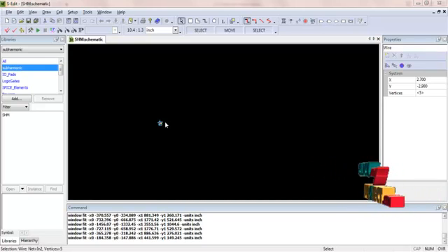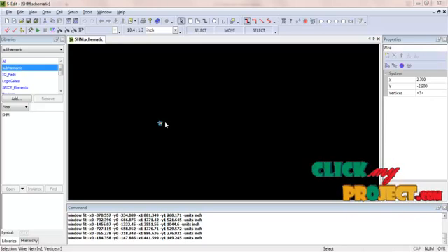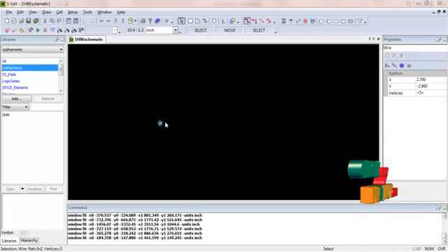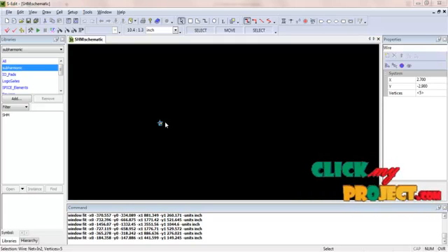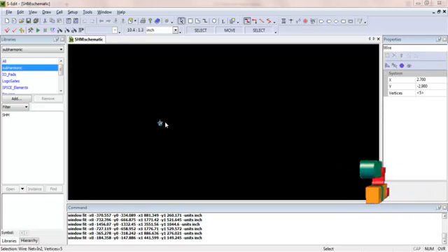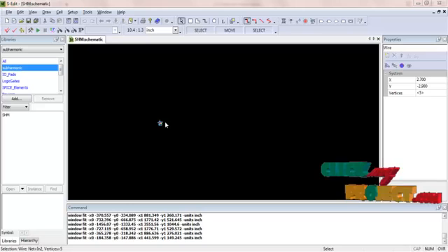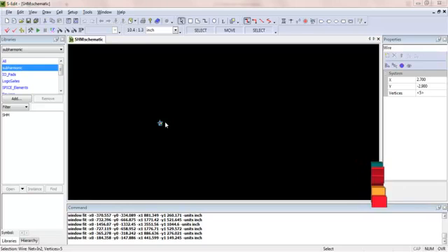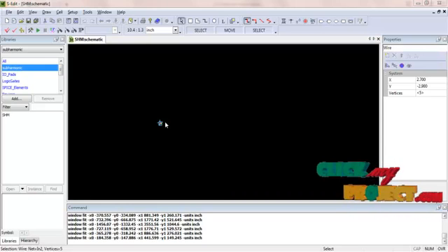M1 and M2 are the input transistors of the RF stage of the mixer. M1A, M2A and EZ1 compose a squaring circuit to generate a low frequency IM2 current. Since the drains of M1A and M2A are connected together, the odd order components of their currents do not appear in the sum of the output currents, and only the even order components are present, especially if the differential two-tone input signal is applied to the squaring circuit. The fundamental tones are cancelled at the output, while the low frequency IM2 current at omega 2 minus omega 1 remains.